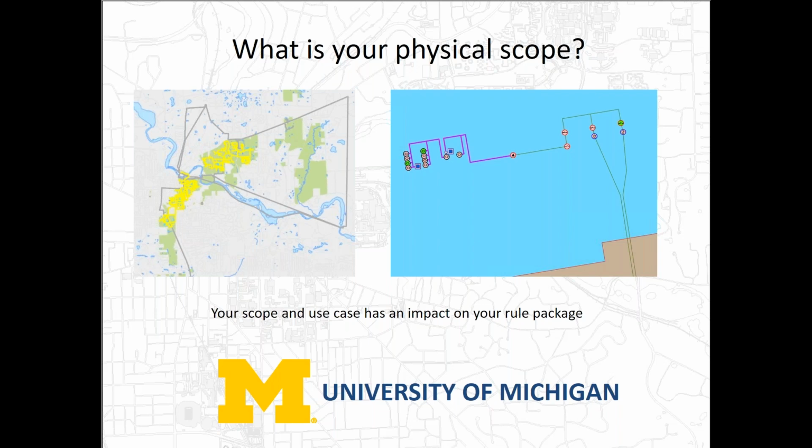The Naperville package has an underground and an overhead conductor type. To transition between underground and overhead, you need to put a riser in, because the larger utilities are all thinking about it going from underground up a pole to an overhead line. Well, that's not how we work in a campus environment. We're going underground through the side of a building into the building.